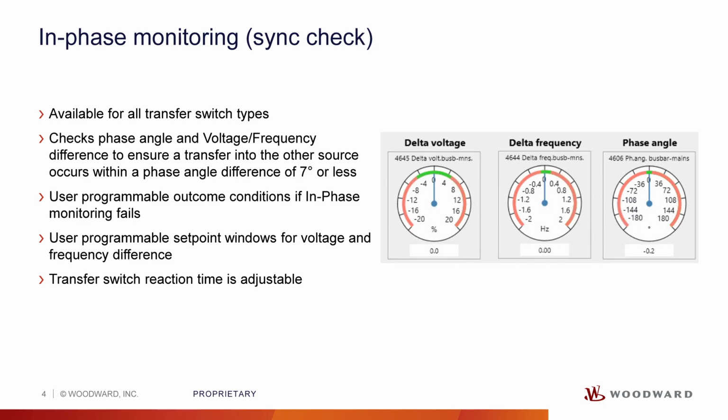In order for the switching to be safe and not cause any disturbances, the voltage and frequency of the generator must be perfectly synchronized with the grid. Mismatched parameters can lead to damage to the installation or equipment. By monitoring the phases, we are able to switch the power source correctly. In-phase monitoring may be used with open, delayed, and closed transition switches. However, let me use a simple example here. This function may be used to improve the transfer with open transition switches.